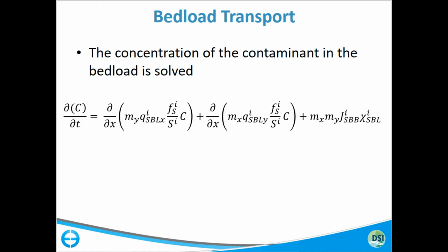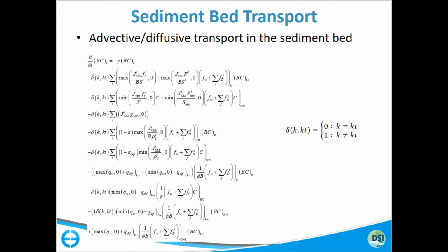So your bed load concentration may be going up and going down, but at the end of the run, or in a quiescent condition, everything goes to zero, and it's all being tracked with full mass balance. That's one of the ways we now can get mass balance even when you add bed load to the transport for toxics. So this is somewhat of a new approach for calculating bed load concentration for toxic transport.